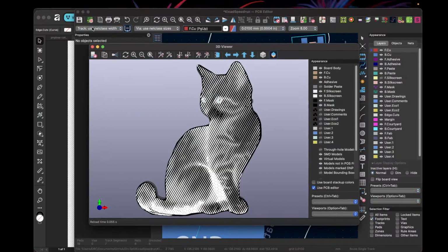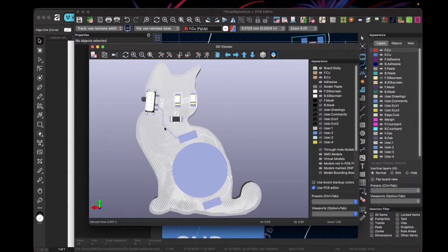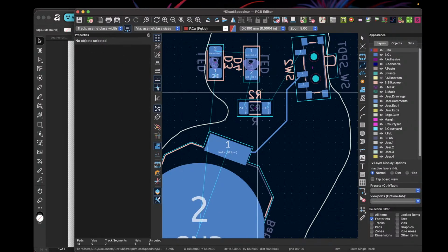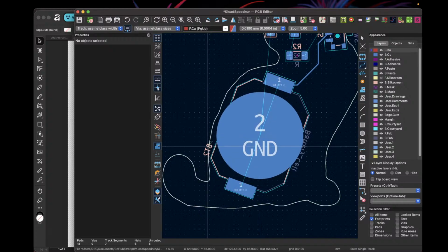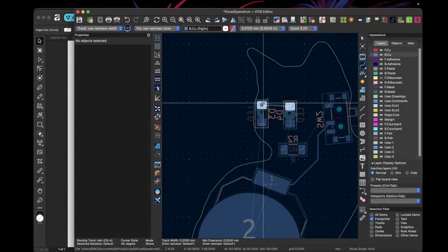You can see it in the 3D viewer. Turn off the back mask. There, you can see that copper trace there. And then that's the back silkscreen. It's the common parts that just show where everything goes. And you can always delete that too if you want to. I typically will get rid of it. Like, I don't need to know that this is BT2. It's fine. Okay, so for this, we'll wire those two up.